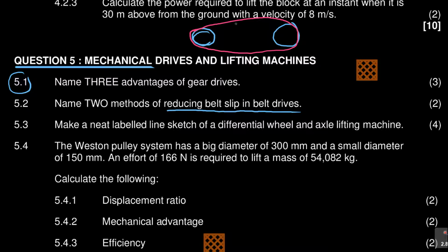Now, they slip because the belt can be slack. When this part starts rotating, the belt comes off. Now, how can you reduce that? Number 1, you can stretch these pulleys apart, bring them apart so that this belt is tense. Instead of it being slack like that, it can be so tight like this. You understand? It won't move out.